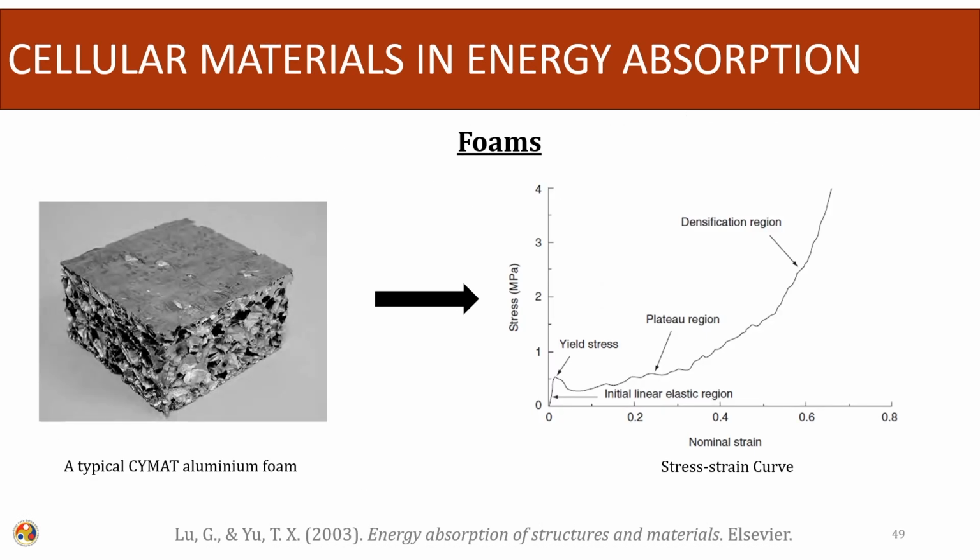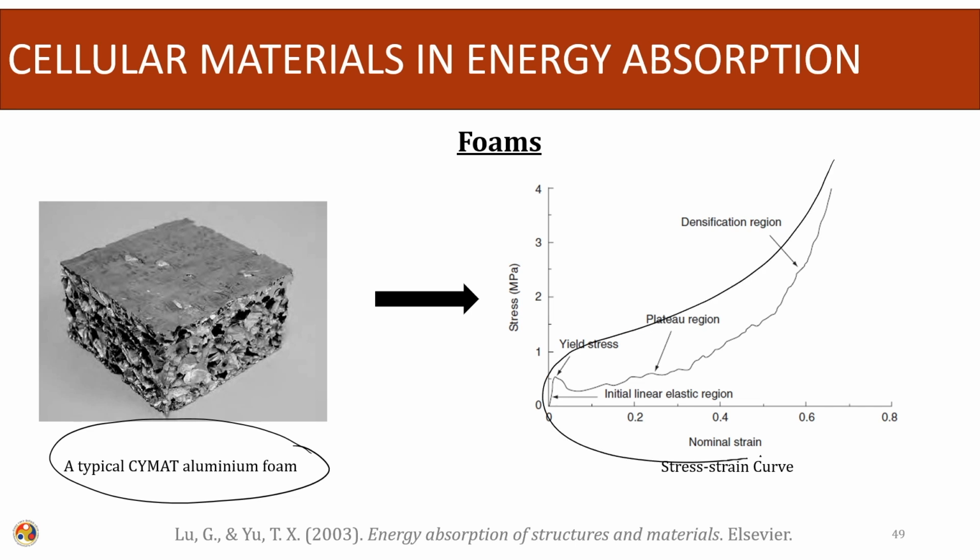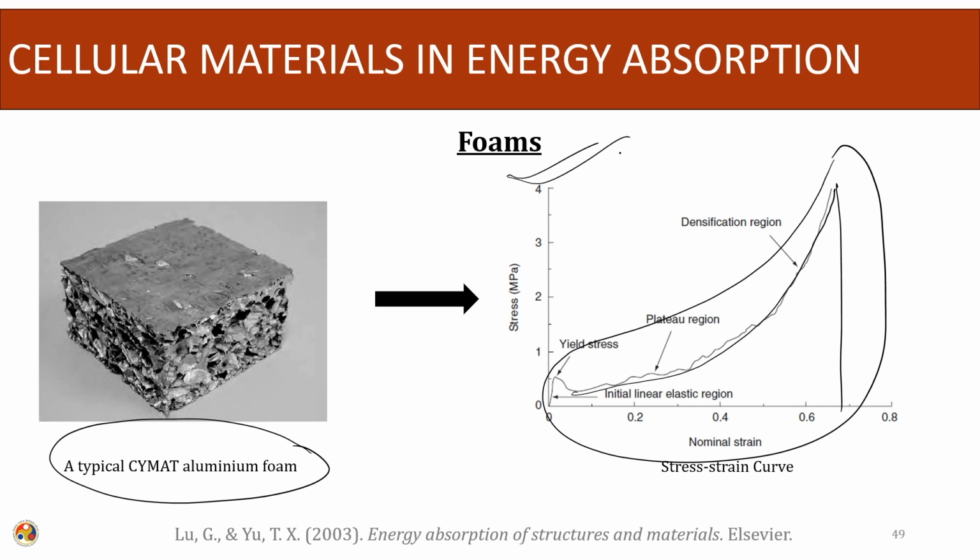Moving ahead. So, here we can see a typical aluminum foam. And as shown earlier, we can see the very large plateau region where the densification is going to occur. The densification occurs, and owing to the large area under this curve, the foam also absorbs a lot of energy.